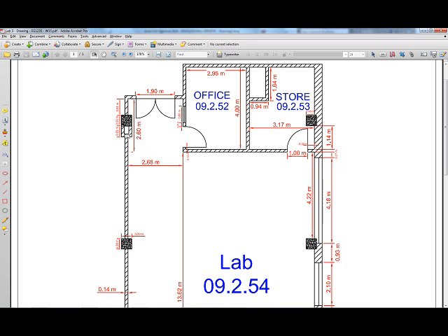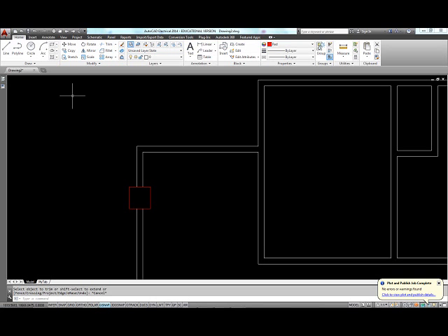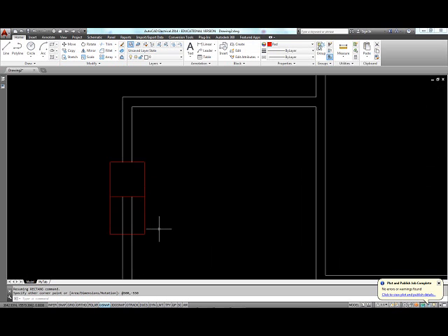Now let's do this duct. It is also at 50 centimeters by 55 centimeters, so we're going to go rectangle from this corner at 500 comma minus 550, enter, and let's do some trimming.